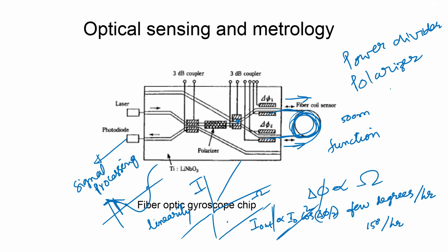Ultimately, what I want to say is that you need a modulator, maybe a phase modulator you can call it, and of course all these are single mode waveguides. Also polarization has to be maintained, single polarization. So there are several components necessary for an application like this, and they could be put on a small wafer like this.